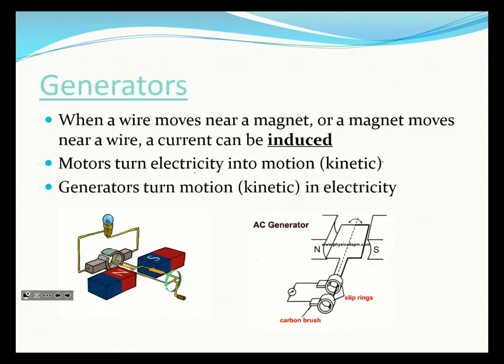Okay. So this is a DC motor design, and with that DC motor, you have this split ring commutator. So you have that split in between there, and you're pulling that crank, and you're lighting up the light bulb. An AC generator, sometimes you'll see this term called slip rings, which sounds a lot like split rings, but it's always two of them, and there's slip rings, and you'd have to be able to identify that as this is an AC generator, and just having one here as a split ring is a DC generator. So DC is split ring, AC is slip ring.